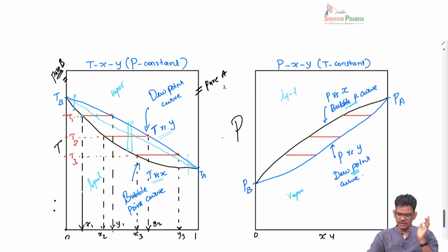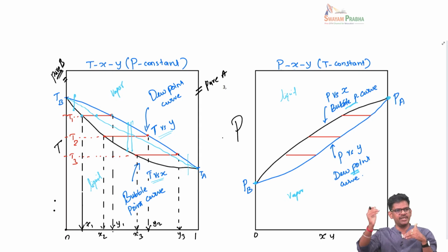Again you have a pure species vapor pressure Pb for the given temperature, and then you have pure component A's vapor pressure Pa. Pa is more than Pb, that you can see here, for the given temperature, meaning A is more volatile. And then between Pa and Pb, you see that there is a coexistence of two phases, vapor phase and liquid phase, both having components A and B.